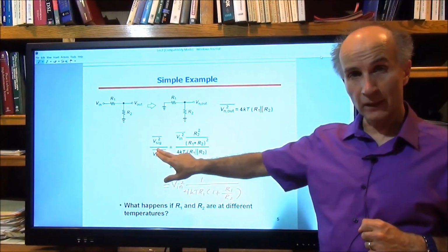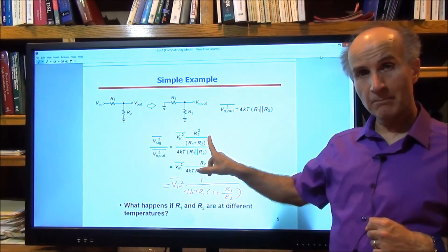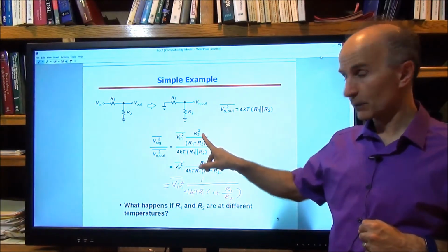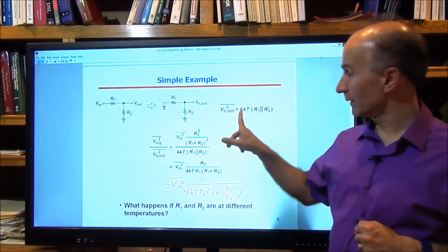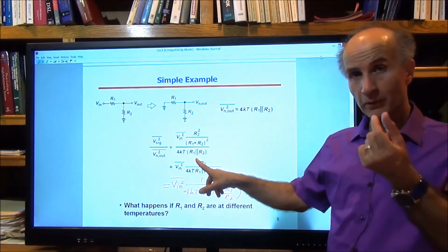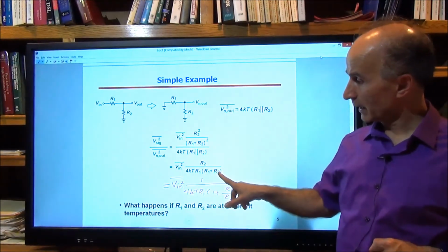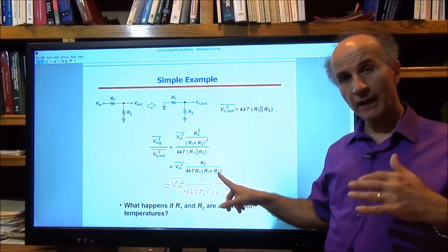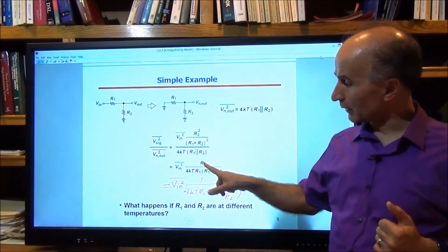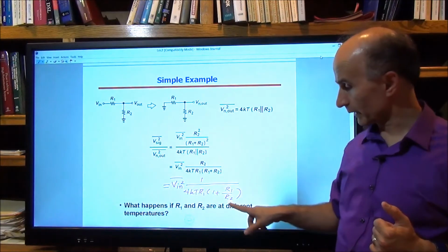The signal power at the output is given by the input spectrum multiplied by the magnitude squared of the transfer function. So it's a simple divider, so these are squared. And then the output noise is what we have, so that's what we get. Both of these are quantities per unit bandwidth. Okay, so we simplify this like so, and I'm still trying to understand the trends for R1 and for R2. So I'm going to divide the numerator and the denominator by R2, and that gives me this equation.